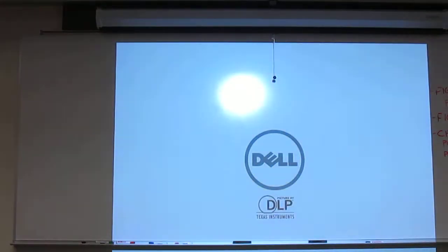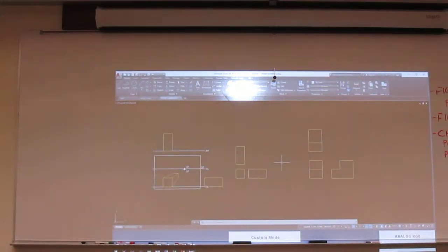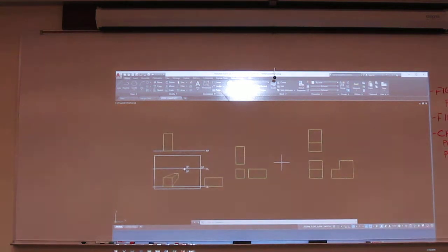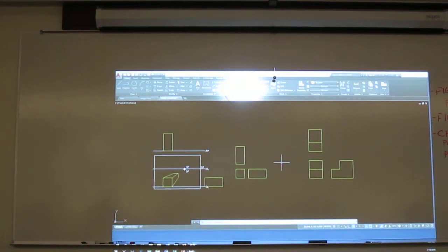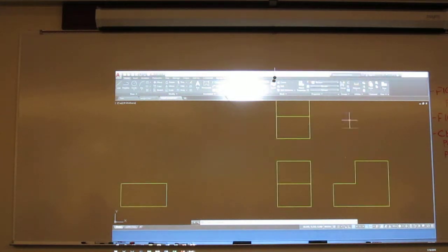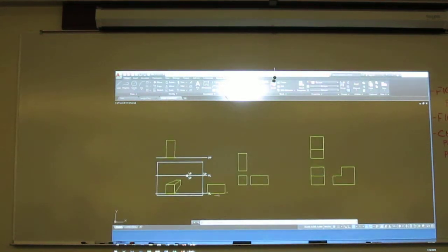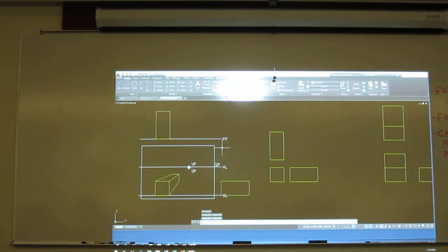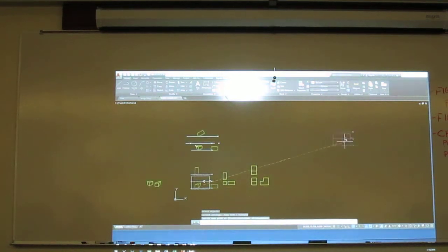If you would, open the drawing we did yesterday. All right, let's do a 1 point perspective first. Now, we have this second object that's right here. Okay, this is the one I'd like to do. So if you would, copy your 1-point perspective stuff off to the side somewhere so we can use it. I'm going to just grab my ground line, horizon line, picture plane, station point, excuse me, picture plane.